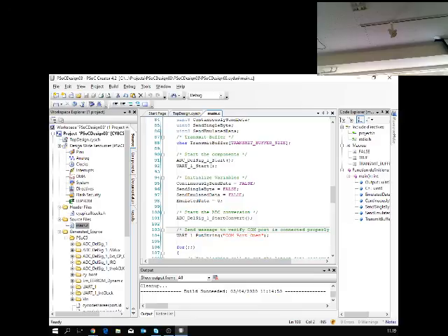The slide. So it looks like this: 1, 3, and 2 is the sliding part. So you can connect this one to VCC, this one is ground, and this one is connected to port 0.0. Then you should start reading some values. But read this datasheet first.